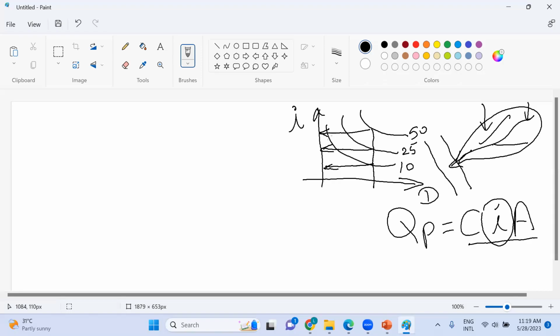You remember the exceedance probability, P(X ≥ a particular threshold). This is equal to 1 over return period. That is how we calculate the hydraulic risk, or the risk of failure in a hydraulic design. So the exceedance probability of a rainfall event is equal to 1 over return period.